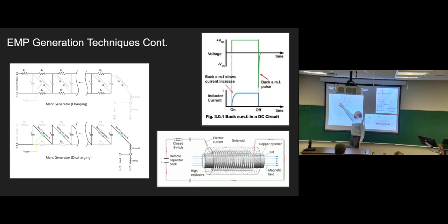And you can see the effective path here is highlighted with dark. So when the spark gaps are off, they're just open circuits. The second the spark gaps close, however, all the capacitors have just lined up and become one massive capacitor for a split second, and they can generate a massive voltage spike right there in that moment. So we're talking, you could take a 9-volt battery and generate 20,000 volts right there. And again, this is made of capacitors and resistors. That assembly, you could probably make it for 20 bucks.